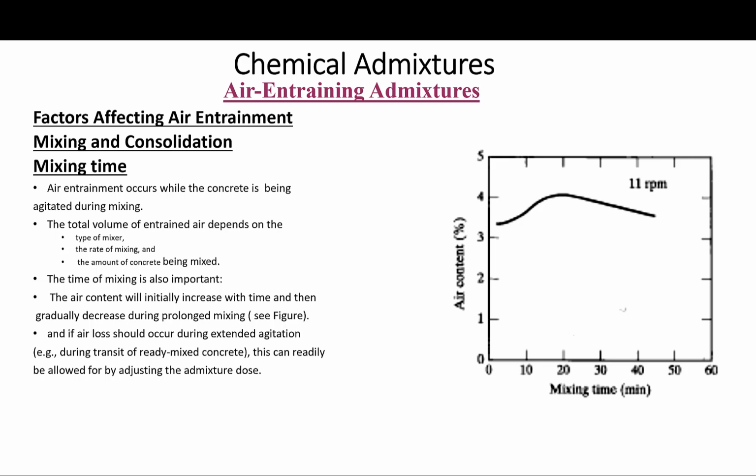So as you can see in this figure here, time of mixing and air content, the air content will initially increase with time and then gradually decrease. Maximum air entrainment is generally achieved during normal mixing times. And if air loss should occur during extended agitation, during the transit of ready mixed concrete, this can readily be allowed for by adjusting the admixture dose.